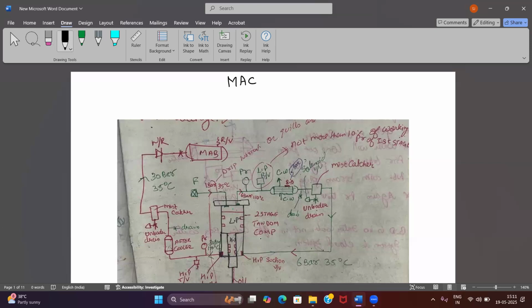Sir, you said that the pressure gauge just before the air bottle and the outlet pressure gauge will show the same reading. What I told you is, suppose you have 3 units, then the third unit pressure gauge will be showing you the line pressure, not the bottle pressure, and the line pressure will be approximately equal to your bottle pressure. Do you agree?